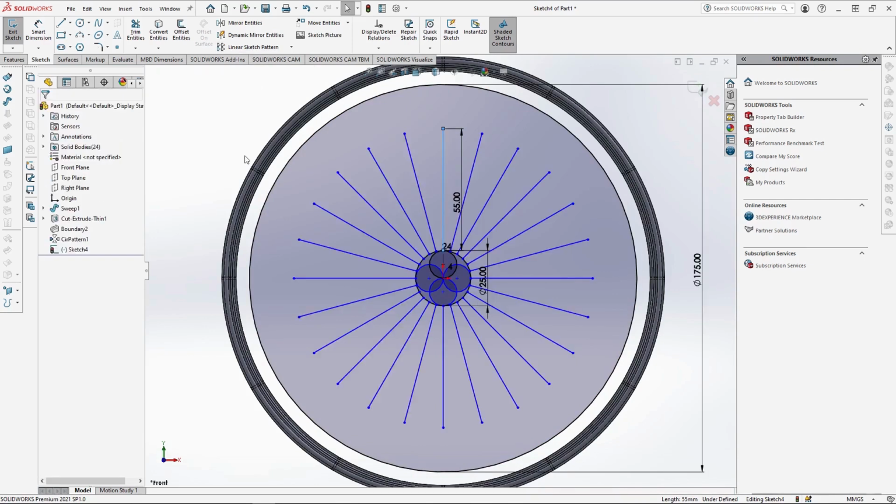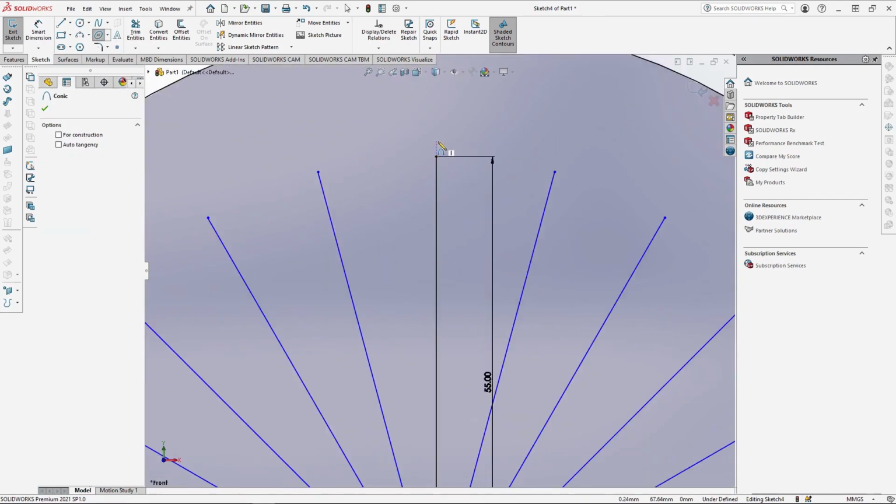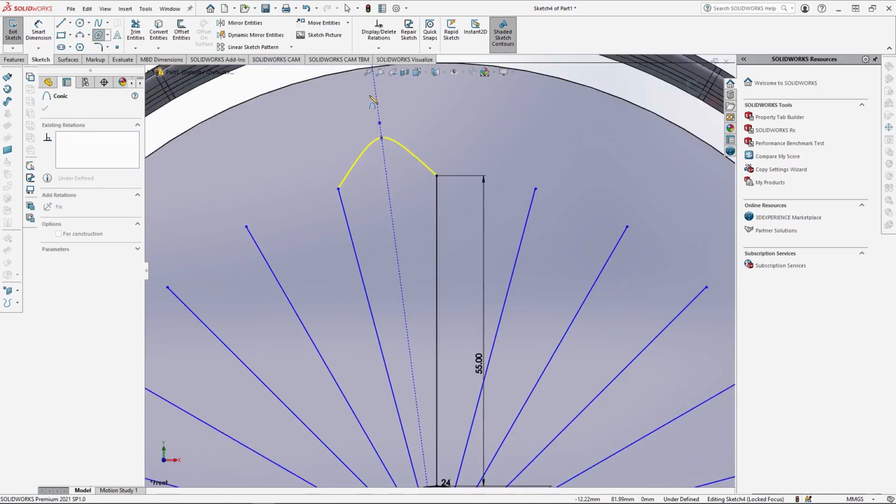To create the flower design, click into the drop down for the ellipse tool and select conic. Use the conic to join up these 2 points, then hover between them until a smart guide appears so that you know you're centre to the lines. Take the conic to here and click once. Then I can move up and down with the peak of the conic until I can see 0.75 as its row value. Then click again to create the conic.